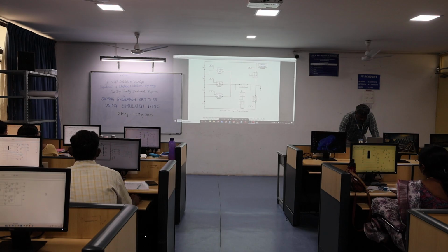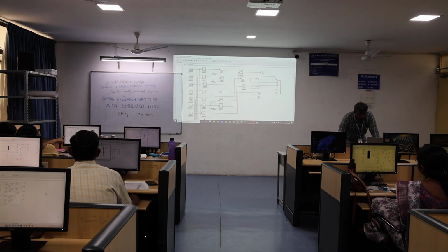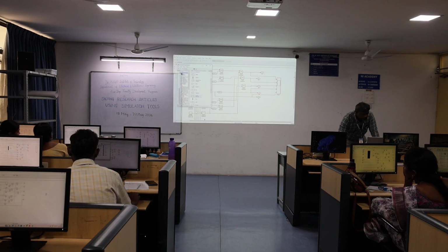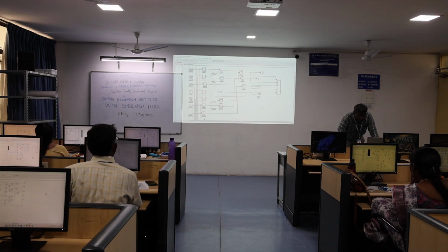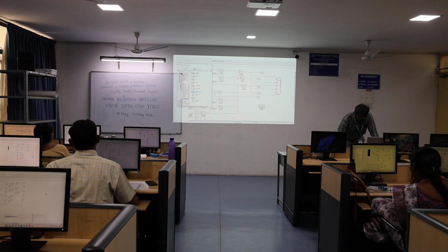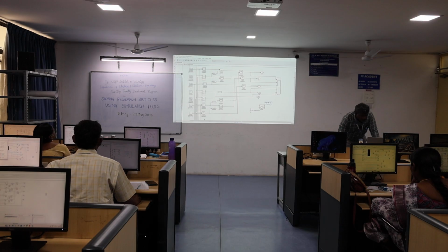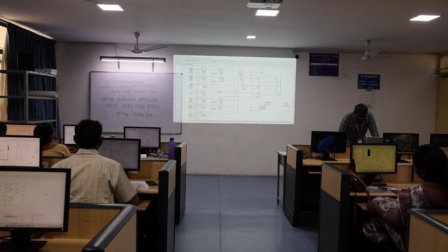Now move on to our simulation. Go to Power Electronics, Specialized Technology, SimPowerSystems, Specialized Technology, Power Electronics. Then take MOSFET. Again go to electric source, VDC supply. Then again elements, so take the series RLC branch. Again measurement block, current measurement, voltage measurement block. So let us take the voltage measurement block. Okay, so now for the load resistance, just change the R value.